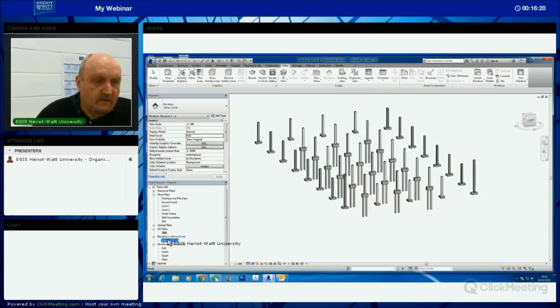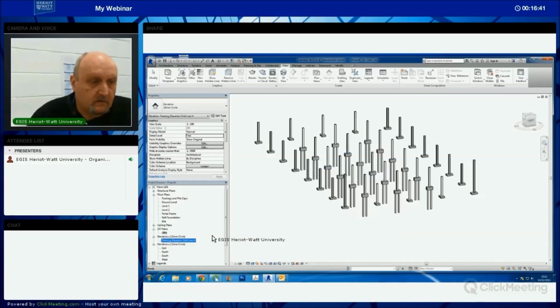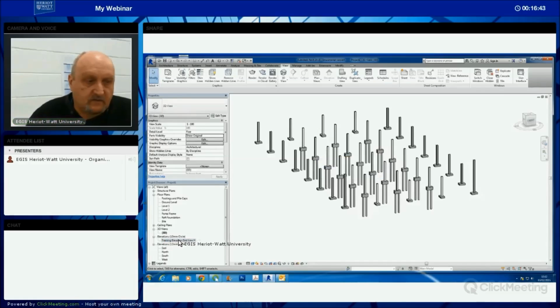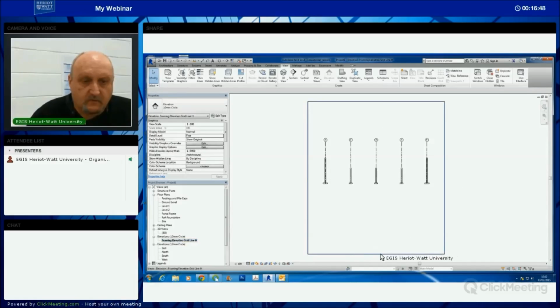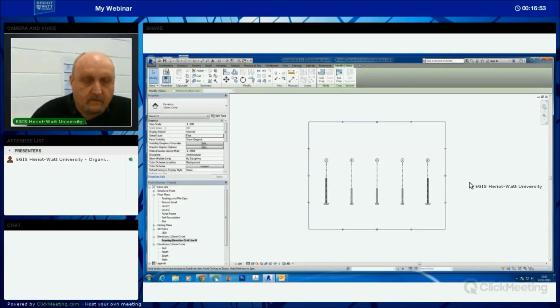And I'm going to go back to this framing elevation and rename it. I forgot to name it, so I'm going to rename it now. It's not just an elevation, it's a framing elevation, so let's give it its proper name. And as a convention, it's usual to say what grid line it's on, and this one is on grid line H. Framing elevation, grid line H, that's its proper name. And the project browser's updated, given that I've renamed it. So I'm going to come in here. I'm going to make this just some white space down there. I don't need all that.